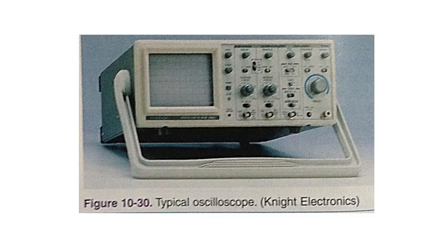Oscilloscopes display waveforms on a cathode ray tube, or CRT. An electron beam is emitted from the cathode gun in the CRT tube. The beam travels between the two sets of beam deflector plates. One deflector plate is for horizontal deflection of the electron beam, and the other plate is for vertical deflection.